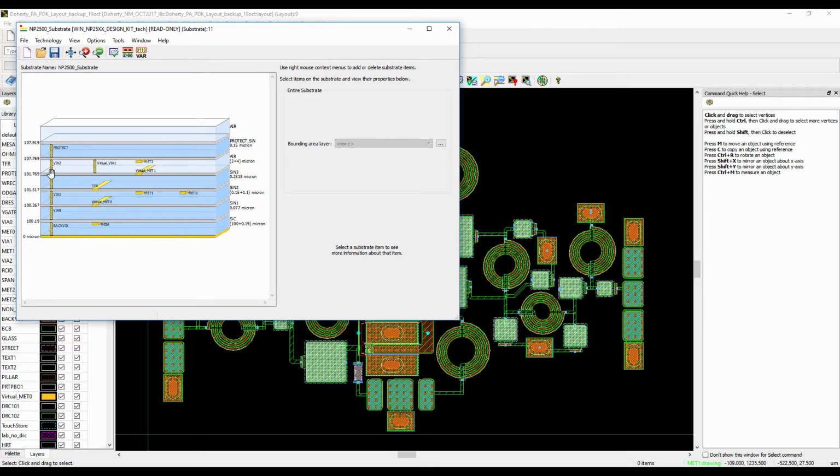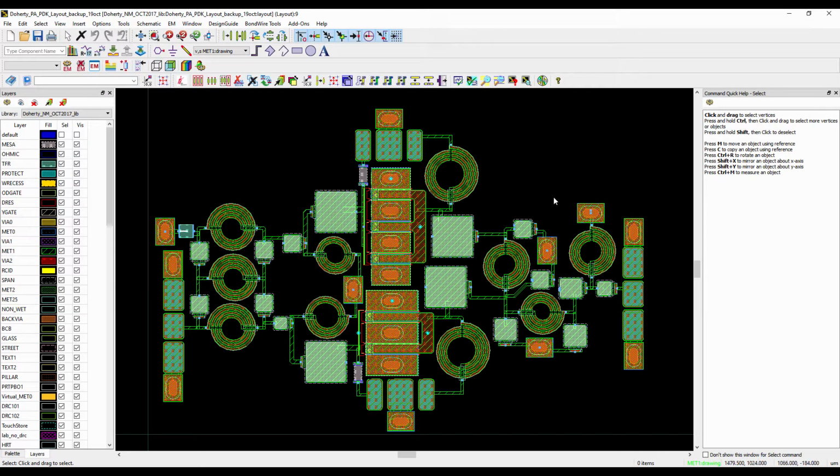So it's a very simple IC process, because most of the CMOS IC processes have 9, 10, 11, 12 layers. So compared to the CMOS process, the complexity of the GaN IC process is very low. Well, the preference for the GaN IC process can be found in high power applications, because they can deal with very high power.